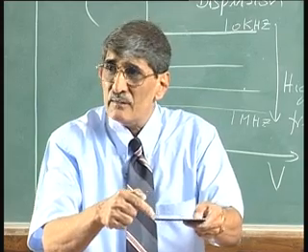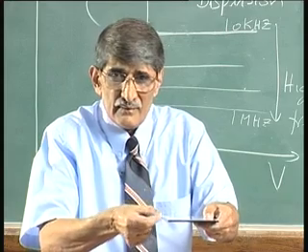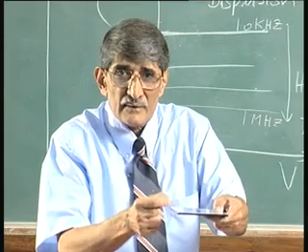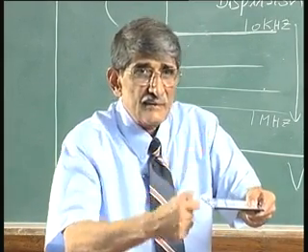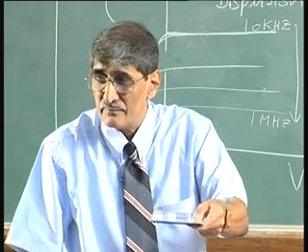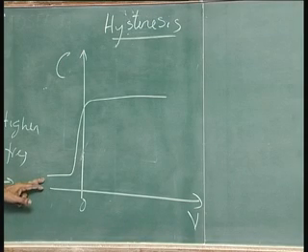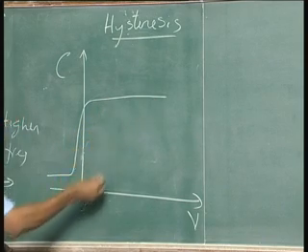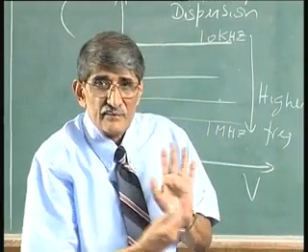When it goes up to the top, its effect on the threshold voltage or the CV is minimum, because negative charge is induced in the metal itself. The difficulty comes if the charge induces negative charges in the semiconductor. The effect is maximum if the charge is near the semiconductor, because it induces an equal amount of charge. So, if the mobile charge moves toward the metal when you apply negative voltage, there is no effect. When I reach here and keep the voltage applied, the mobile charges have moved down. Now, the entire curve gets shifted to the left.